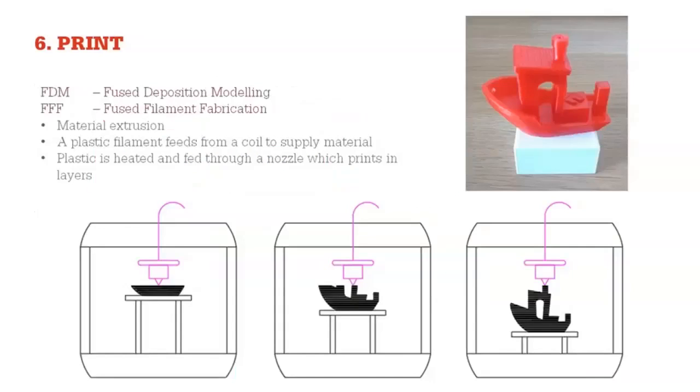So probably the most common or most known method and the most affordable method at the moment of 3D printing or 3D printers is what we call FDM, Fused Deposition Modeling. This is what a company called Stratasys patented many years ago. And these days, a similar version, FFF, which is Fused Filament Fabrication, which now other companies provide. So they're both the same technology, they're just one's a proprietary name and the other one's a generic name.